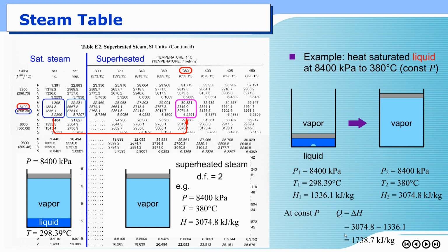Okay, because right now, in order to convert liquid water into pure vapor, it requires latent heat in addition to sensible heat. Previously we just needed sensible heat, but now we also need latent heat in addition to sensible heat, and you know that latent heat is much larger than sensible heat. Okay, so this is the way that we can read the information from the table.